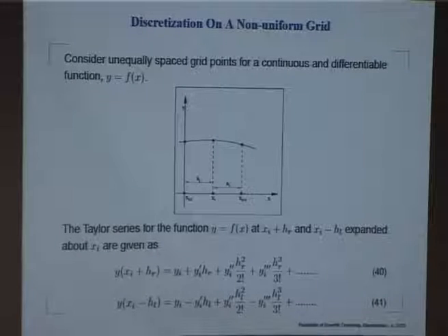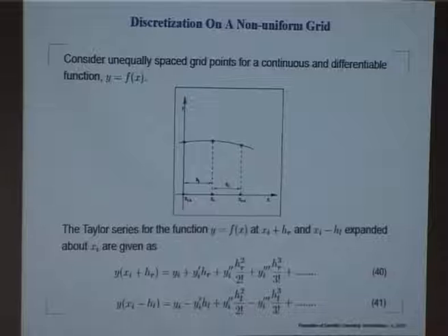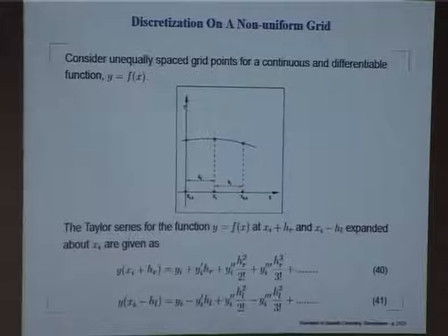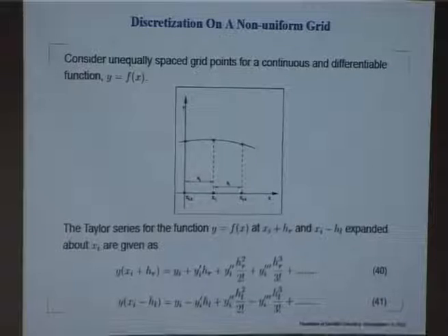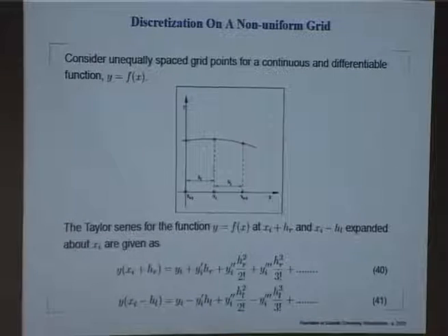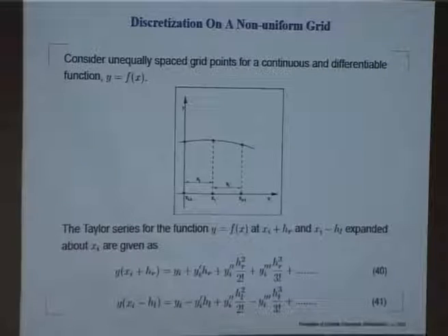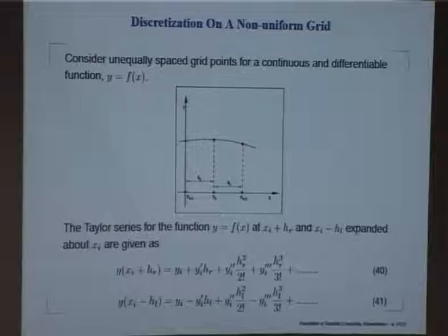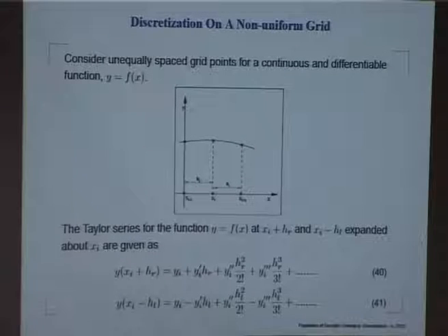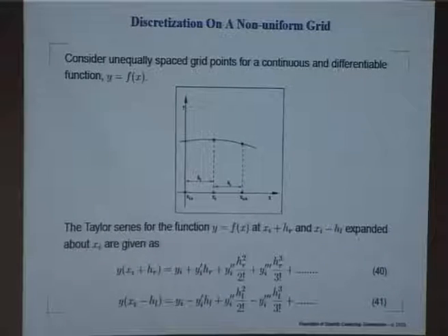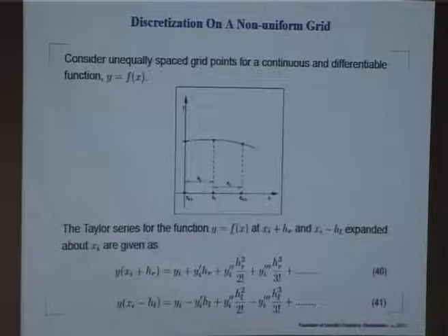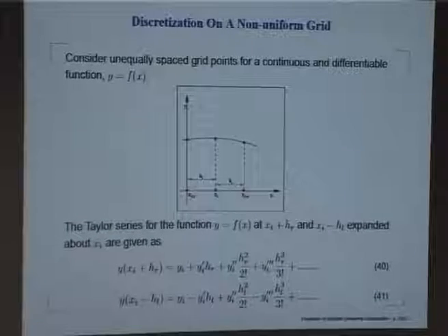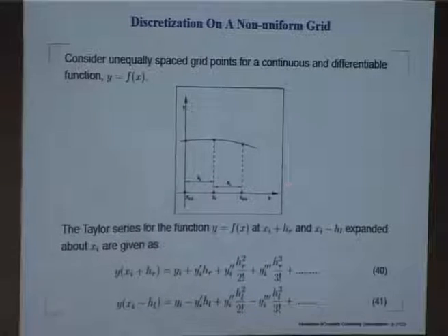It would not be very smart to continue with that kind of discretization for the whole domain. That would amount to taking an astronomically high number of points. So, what one ends up doing is basically take points which are non-uniformly distributed. So, wherever you have flow gradients, that is where you have finer spacing. As you go away to regions where the gradients are not so large, you can keep on increasing.